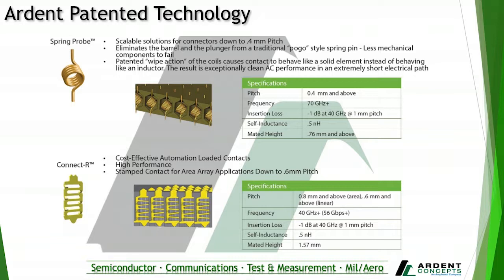Our compression contact technology is a low compression force solution, requiring compressive loads within familiar ranges similar to that of a pogo pin. The ability to offer these low compressive force contacts allows our connectors to be used on a variety of PCB materials, including some softer, high-speed materials like flex PCB.